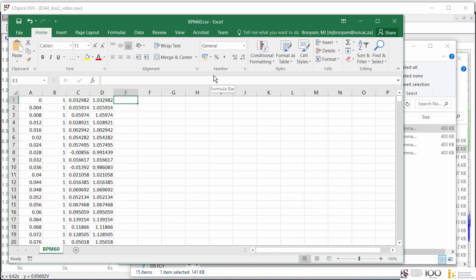So if you wanted to make your own, let's say your specification was 25 millivolts, you'd take this one here, divide it by 100 millivolts, and multiply by your own specification, 25 millivolts. That gives you the AC component. Then if your DC component was, let's say, 2.2, you multiply that by 2.2, and then the sum of the two is just that, add this. So that gives you the signal that you can work with.